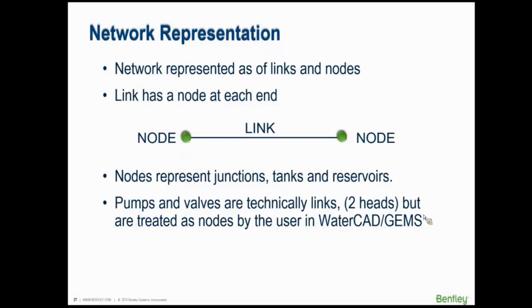And the head loss equations are nonlinear, which is a bad thing for solving numerical equations. So you don't want to calculate pipe networks by hand. It would be very, very time consuming, very, very difficult. Instead, what you do is you use a computer model where the size of the model can be very large, and you calculate systems that manually you just could not calculate by hand.